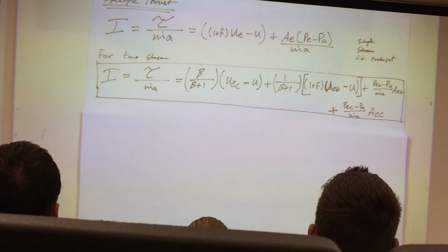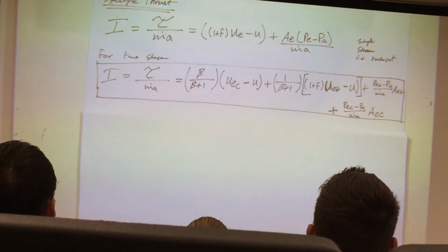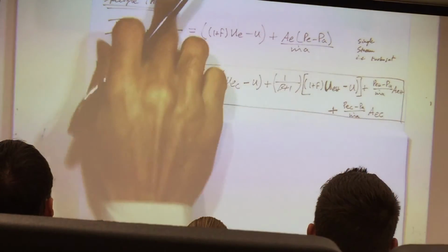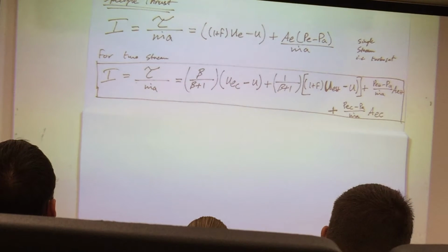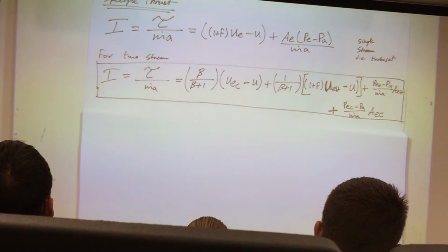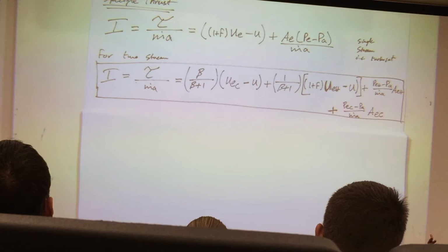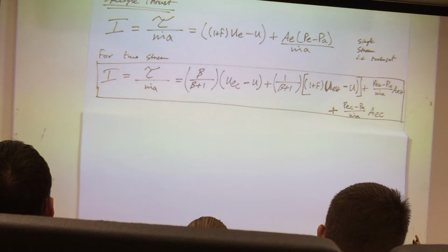So it's a good question. Hunter is asking, most likely you're going to try to design your engine so that the exit pressure is equal to your ambient pressure, but that's not always the case. So for military engines, you're always going to have oblique shocks at the exit. Or you're going to have a normal shock. In the problem that you're doing, you have a normal shock at the exit. So that's not your exit pressure. The exit pressure is different than what's outside.